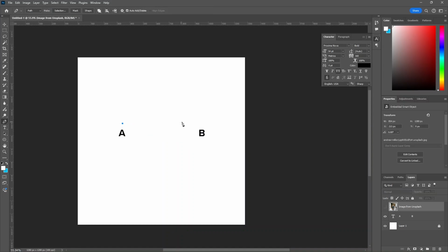So with the pen tool, you can create curves, all right? And to create a curve, you have one point here and another point here, and you just have to drag, all right? The more you drag, the steeper the curve gets, right? And as you can see, this line is called a handle, and this line affects this curve, all right? This line is going to affect the next curve that's being created. So when I press another point, you realize that this curves around. It doesn't go straight down. It curves around because of this line.